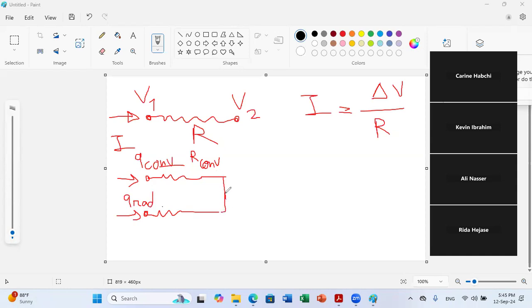So I can represent my thermal system or my heat transfer system by an electrical circuit using the electrical analogy. When they are added together, they will move through the envelope by conduction. So I have now a total, the summation of these two from the energy balance, Q convection 1 plus Q radiation 1, that will move through the envelope by Q conduction. And of course, the material of my envelope will resist this heat transfer by developing a certain resistance to conduction that we will see how to get.